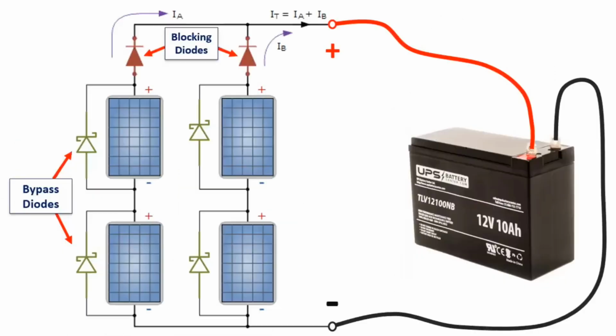Another example of usage is solar panels. 2 groups of diodes, bypass and blocking, are used in the connections of solar panels. Blocking diodes are used to protect the panels against reverse current from the battery. Normal silicon diodes are used here. Bypass diodes are used to transfer the generated current directly to the battery. Here too, Schottky diodes are preferred since the forward voltage drop is very small.